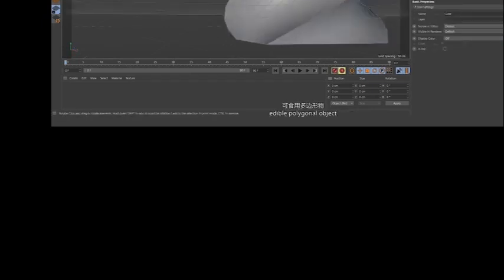It's in this Mesh menu. It can also be accessed by right-clicking the mouse. Applying it creates a duplicate of the selected model in the form of an editable polygonal object. When using any deformers, they will be applied to this polygonal model and locked.